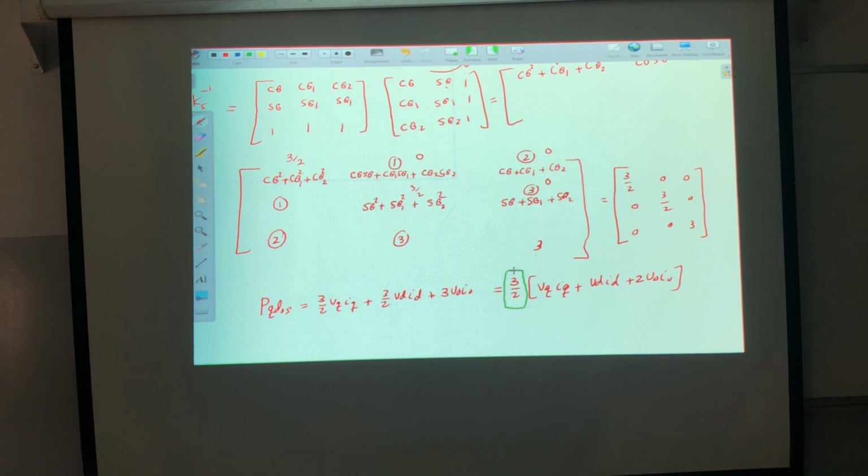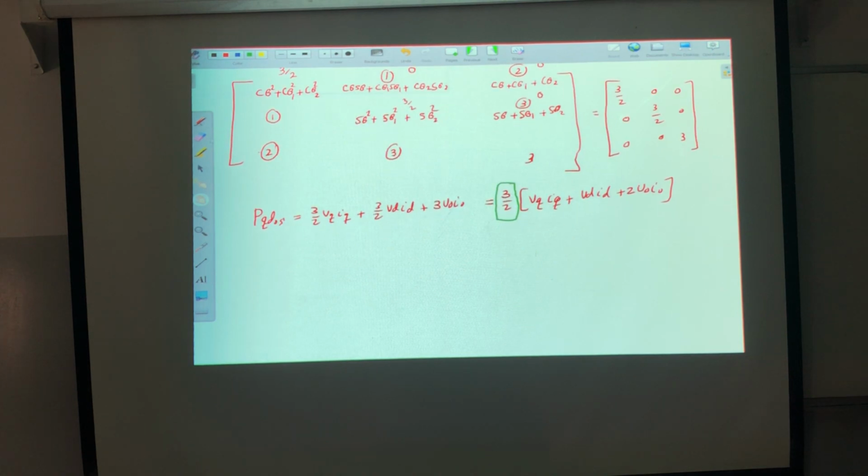So it is left for you to design the scaling factor in order to preserve the power, which means that I need to find now a modified KS. KS is modified and contains 2 factors, alpha. Here, cosine theta you cannot touch. Cosine theta 1 you cannot touch. Cosine theta 2 you cannot touch. Sine theta, sine theta 1, sine theta 2 you cannot touch. And here let's assume it is M, and M.